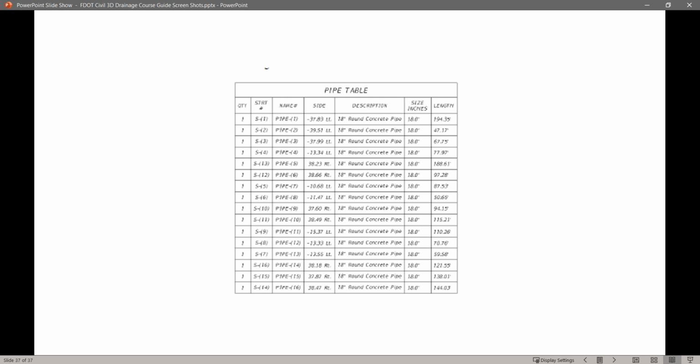Exercise 6.11. Add pipes only to structures. The next steps will show you how to add only pipes to structures. In the next steps, you will create pipes that connect to structures. The table below can be used to assign the pipe names as they relate to the starting structure name. You will see how the order affects flow direction.